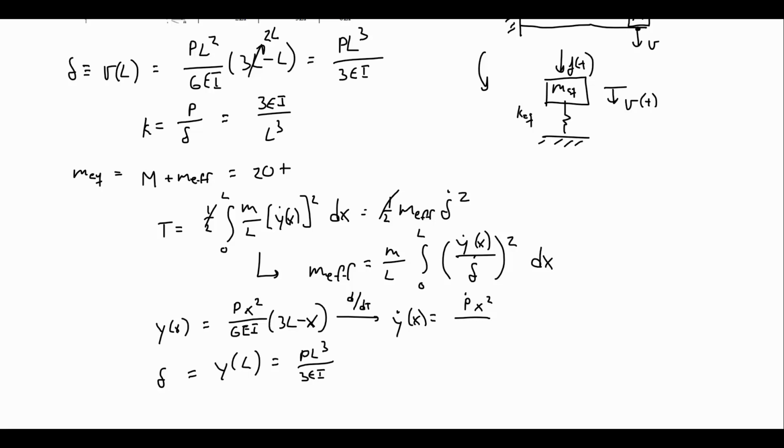So in this particular case, x is not a function of time, but y is. E and I we're saying are constant in time, so they're not affected. x squared over 6EI times (3L minus x). And then here, same idea. If we differentiate both sides, the velocity at our chosen degree of freedom is going to be P dot L cubed over 3EI, and that's it.